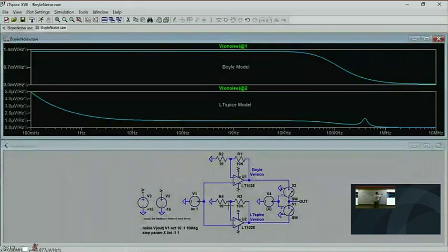Now the common mode range of this will go to the positive rail, maybe even a little above, but it won't go to the negative rail because this current source needs some voltage headroom to keep behaving like a current source, because it's some active circuit with semiconductors. So this will go to the positive rail, but not the negative rail. So to make a rail-to-rail op-amp, you have two input stages. One is N polarity, and the other is P polarity. Because this stage will go common mode to the negative rail, but it can't work to the positive rail because this current source needs voltage headroom.